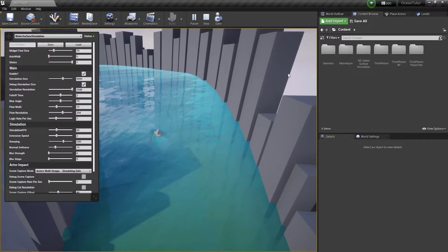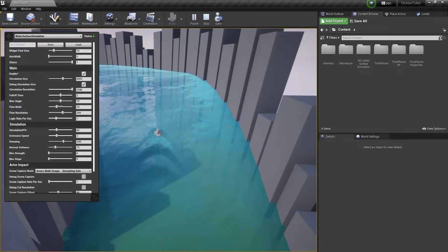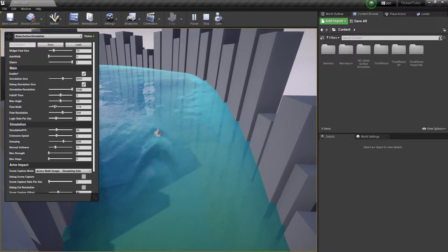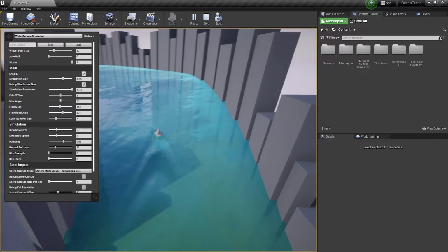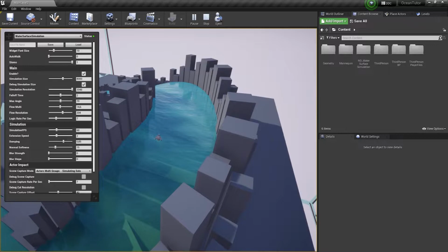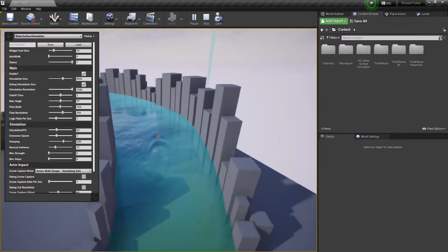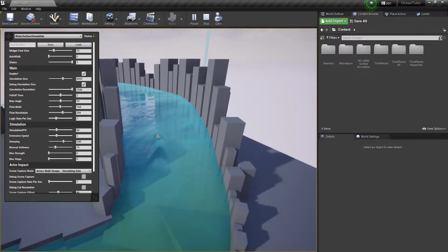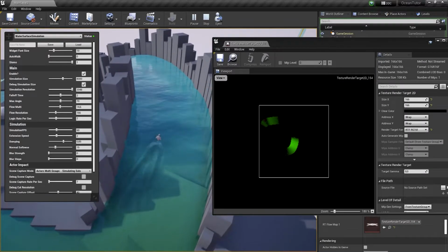And you also need to set flow multi greater than 0. The larger it is, the stronger the effect. However, it's a bit expensive because it adds a new scene capture that captures the scene every tick. So if there is no need for this, it's preferable to disable this parameter. For this you need to set flow multi to 0.